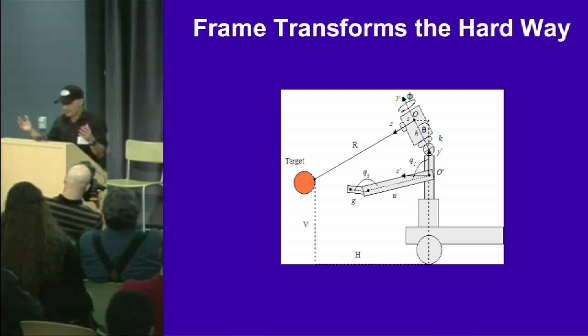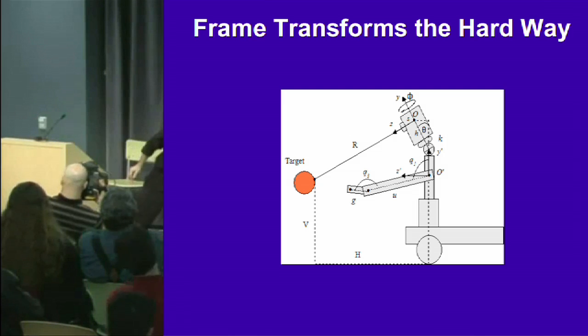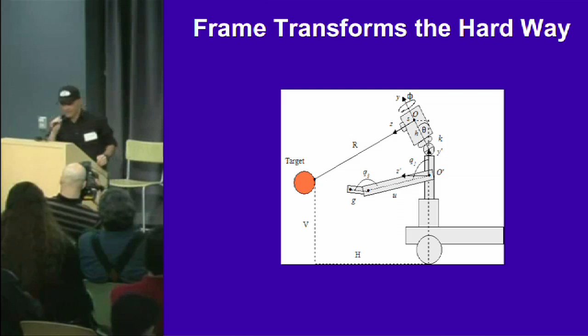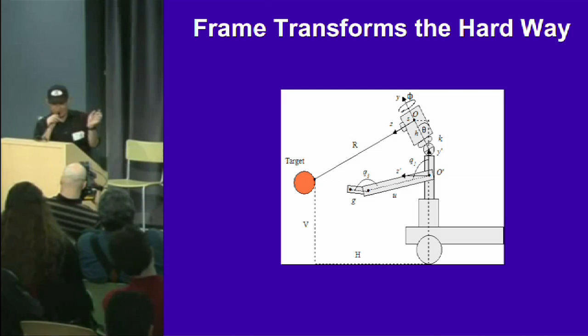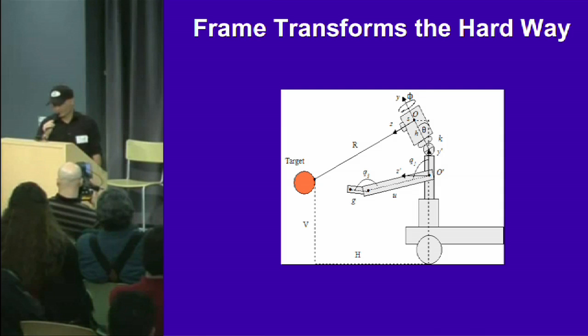And at the same time, I have a little sonar sensor on the head of the robot that gave me the Z coordinate out to the balloon. So now we had the 3 dimensions of the object in space, and I wanted to move the arms into position so it could grab the balloon. So that's the inverse kinematics problem, and I wanted to solve it just for 2 degrees of freedom, and it's been done a million times, and all it requires is high school math.